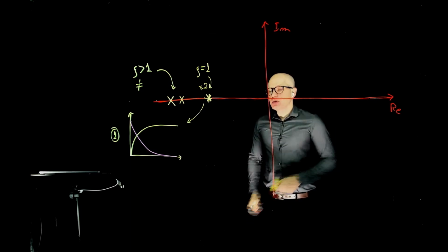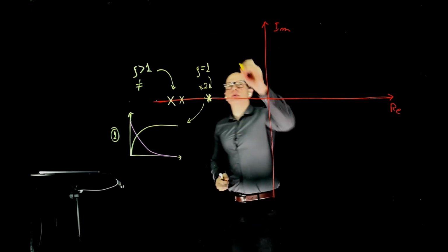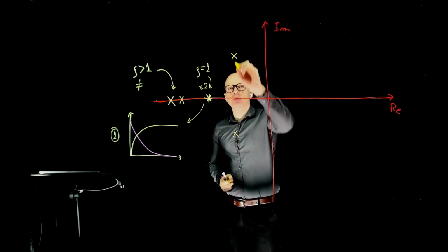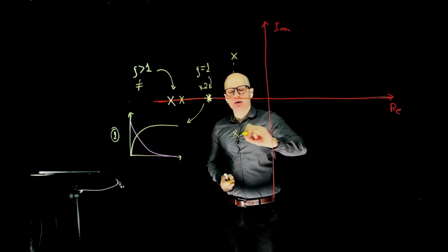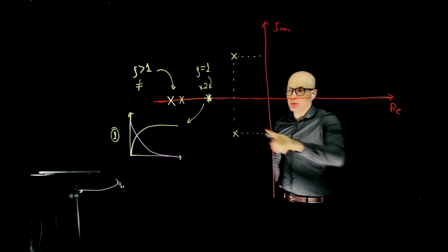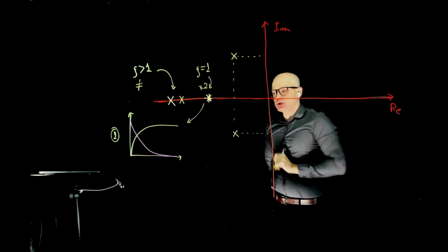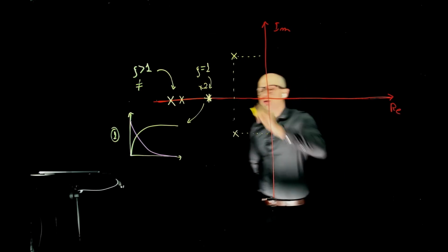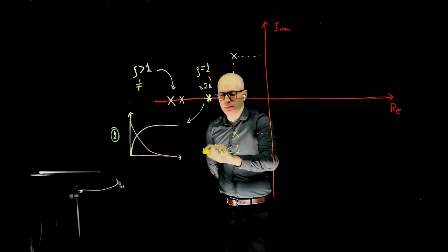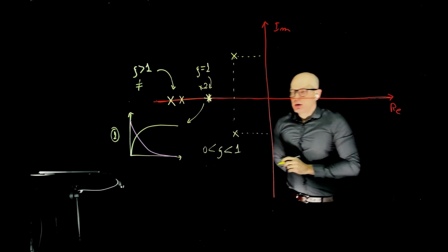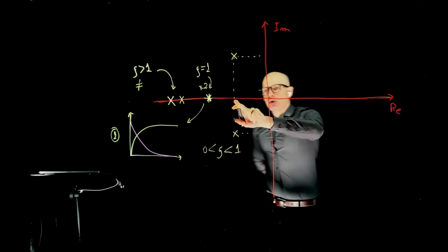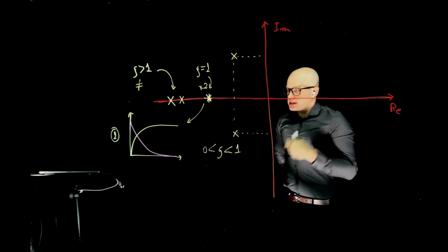If you keep decreasing the damping ratio, we reach a point where now the poles will break away from the real axis and they become complex conjugate. Meaning now that they have both a real part and an imaginary part. This occurs when zeta is less than 1 and greater than 0. Okay, so imaginary component, real component. The real component is still negative.